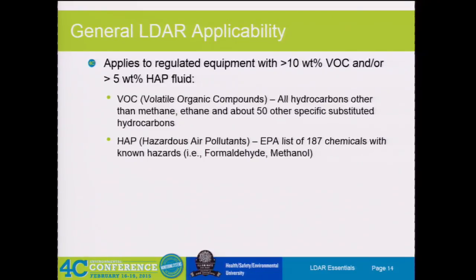So general LDAR applicability applies to regulated equipment with 10% by weight or more of VOC and/or 5% weight HAP. A VOC is all hydrocarbons other than methane, ethane, and about 50 other specific substituted hydrocarbons. So basically you can go anything about C4 and above.